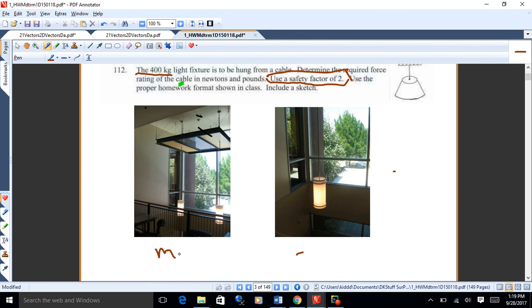I think what you're going to do here is use mass times gravity is equal to weight, right? Because weight, another word for that is a load. It's what we design for, okay? So just be sure to get that mass into a weight. And then to get your load, you'll take the weight times 2. That's the safety factor, okay? That's all.